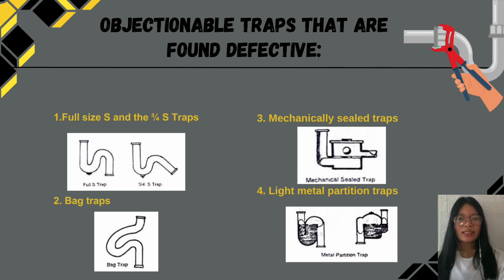Okay, so the full size S and the 3/4 S drops, also known as S drops, are considered objectionable and defective because they do not maintain a proper water seal consistently. Ang bag traps naman, these traps are unreliable and prone to leaks or malfunctions, leading to drainage issues and potential health hazards.